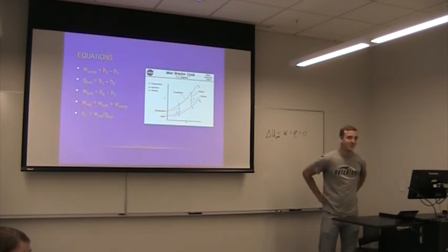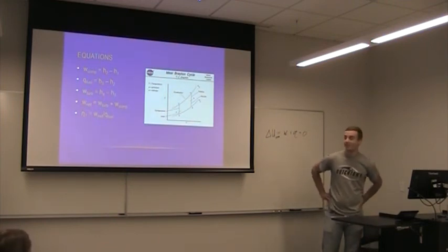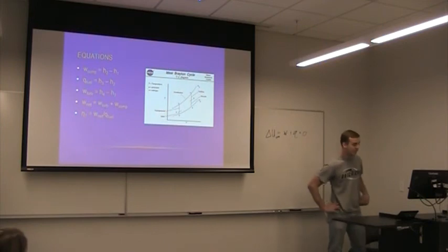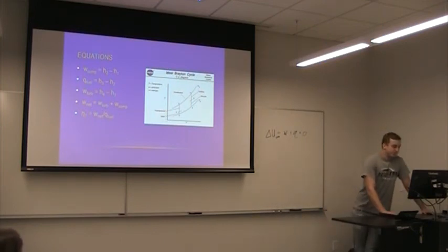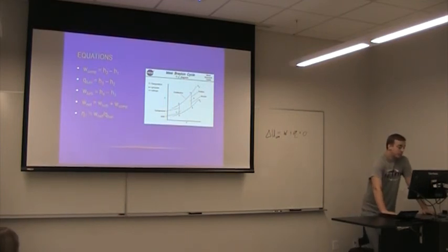See, if you stuck with that diagram, I would have changed the numbers and the equations you wrote down. Right? If you look at the graph that you have, what is the work of the compressor? Using the numbers on the graph, what are the numbers? H3 minus H2, yeah. And then what's Q fuel? Which number is that for you? What two numbers are those? Q fuel will be H4 minus H3, correct? And then turbine is H5 minus H4. Oh, it's your sign convention. Yeah, that'll work out. You still keep your next one, okay, fine, that's fine.